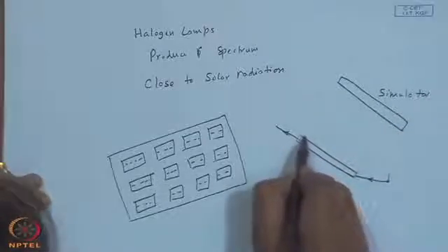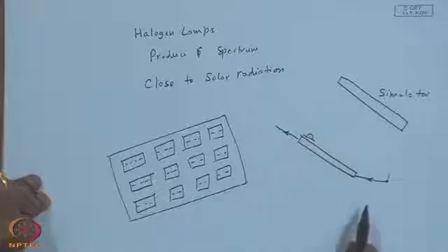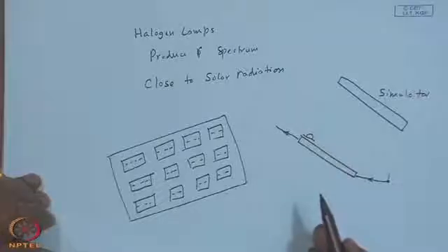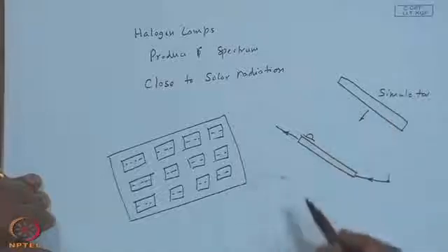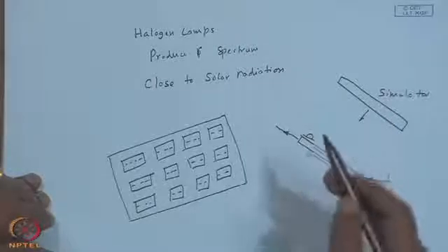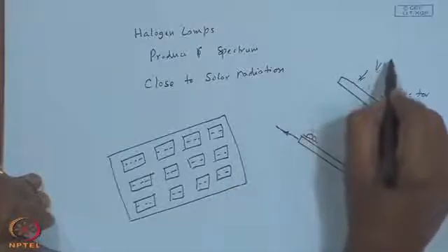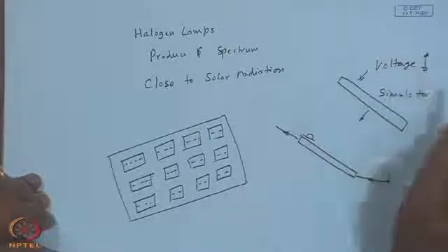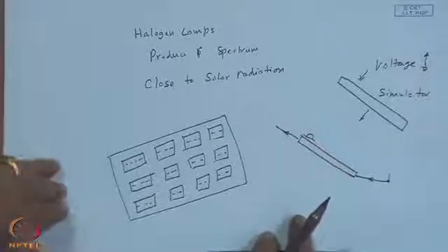and you use a pyranometer on the collector surface and ensure whether the intensity is uniform or not, and if it is within plus minus 5% or so, it is okay. If necessary you can move it nearer; if you want a lower intensity, move it away, that is one way, or change the voltage. Voltage applied through a variac can be up or can be down, of course, within 220 volts supply limitations, and then you can go down to 100.